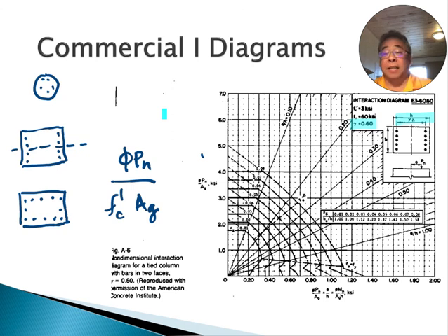And that is not constant, because the bars are actually kind of big in columns. Depending on the overall dimension of the column, if you have a very large column, gamma is high because the cover is insignificant relative to the overall width of the column. But if the column is smaller, gamma can be lower. In this case, gamma is 0.6. It can go up to 0.9.